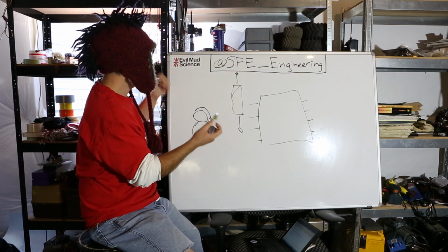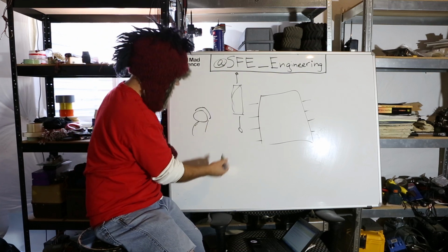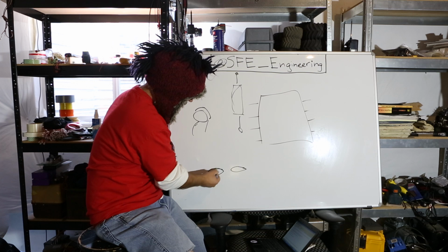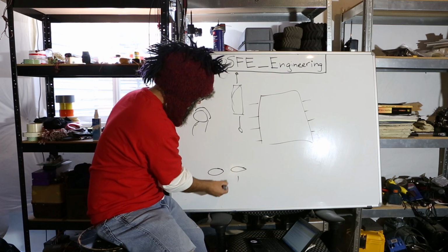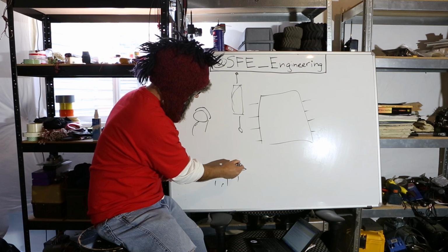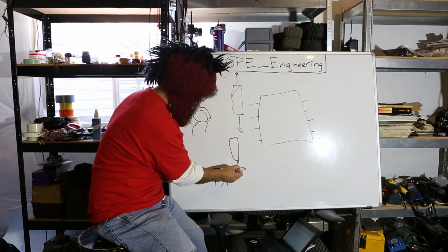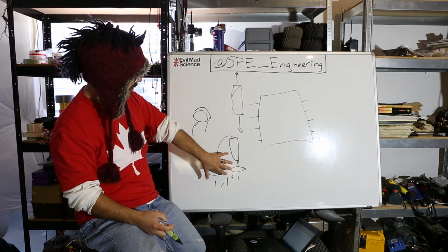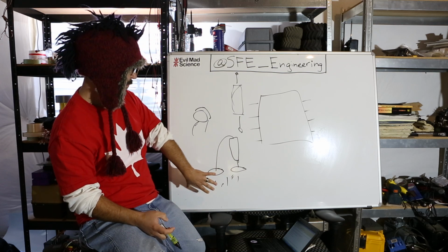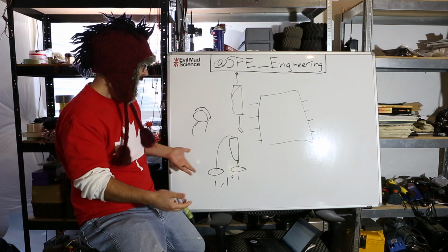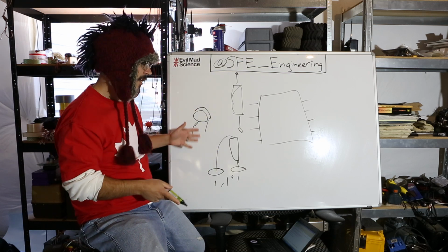But one little trick you can do with these is physically stand them up. To give you an idea, you've got one via here, and you put the other one right here. So this will be 0.1 inch spacing, and then you take your resistor, put one pin here, and just stand it up, with one pin there. So are your traces actually shorter? Well, it's probably a wash in the end, but the physical space it occupies on the PCB is not as big as it would have been otherwise.